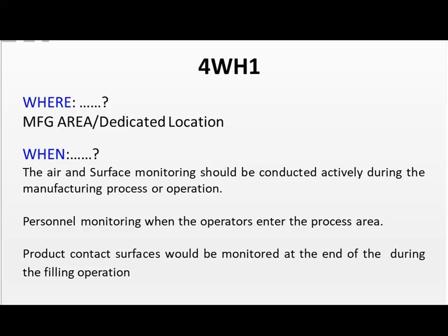We also monitor contact surfaces at the end and the beginning of a fill, and that's typically how we do it. Now, we can put the monitoring on a rotational basis because we do want to catch the middle of the fill as well, but we're very interested in the beginning and the end, and we're interested in the filling operations. These are the critical operations. Then we're going to monitor the entire suite, whether we're filling or mixing or whatever we're doing, but these are the critical places. Typically it is the fill, and we want to be sure that we capture the environment at the beginning and the end of our fill.